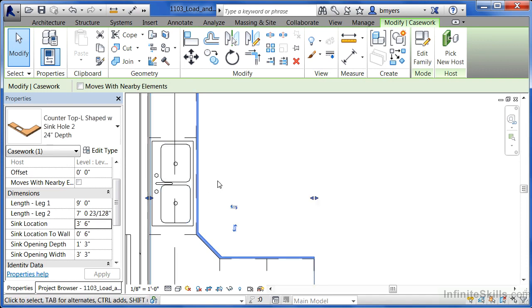This process that we just did is not just for such things as sinks. Pretty much anything that would be considered a component family would get placed in this way. There's nothing wrong with 2D if you only need to see it two-dimensional in that specific view. In the case of a plan view, if this is going to be the only spot I would ever see these sinks, then loading in two-dimensional sinks is fine because it'll show up and document appropriately.